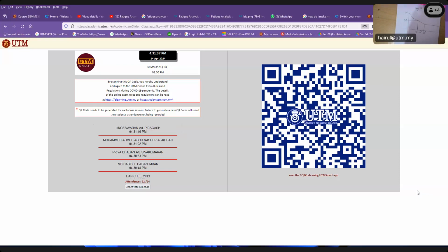Pulley at A, the shoulder is between. The shoulder is after the pulley, before pulley B, but the groove on the left is before the pulley, so it has no torsional stress. It only has axial stress and bending stress. Bending stress uses the moment at that point from the moment diagram, not at pulley A. Use the Pythagorean theorem at that groove position. Understand? That's why you should look at the solution.